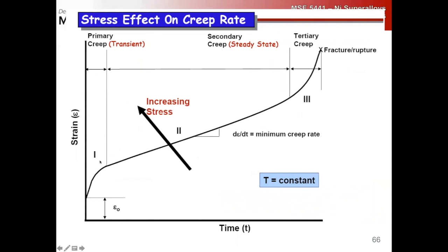So you have an extended primary creep region, which never really saturates out to a minimum, long linear region before damage happens. So this primary creep curve just gets extended way out sometimes. But most of the microstructural changes in the material are happening in this primary creep region.